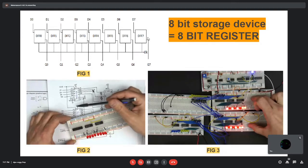Okay, so nothing more, a register is like latches. If someone says 8 bit register, that is 8 latches together controlled by a single clock. This person has done this practically. Do you see here 8 LEDs? The LEDs are telling you the state of all the 8 latches.